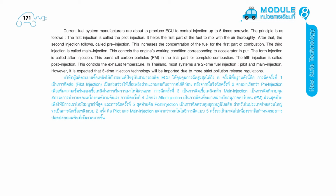The third injection is called main injection. This controls the engine's working condition corresponding to accelerator input. The fourth injection is called after injection. This burns off carbon particles, PM, in the final part for complete combustion. The fifth injection is called post-injection. This controls the exhaust temperature.